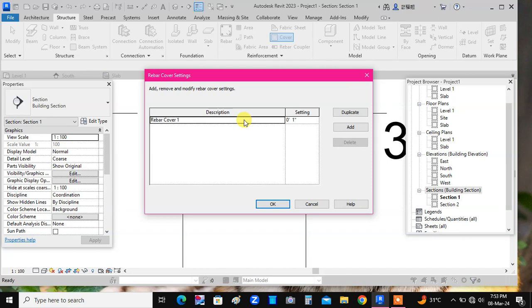Remember, in the beam under consideration, we will place main bars of 8 mm diameter. Remember, all these details will be given by your designer, and then using those drawings you can select proper dimensions for all the reinforcement or the rebars.